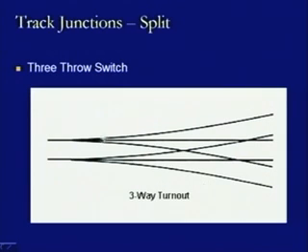So, that is why the 2 pairs of tongue rails need to be provided here, and here there is a crossing, as we can see, and this is a V shape. So, this V shape will be like this, and then this rail which is coming this way will have a wing rail at this location as well as this location.